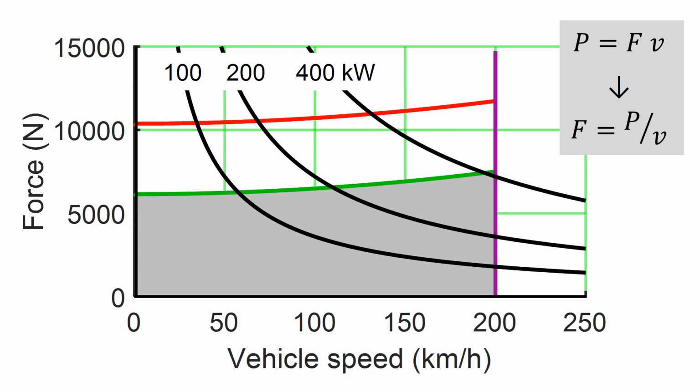Changing requirements does not influence the rolling resistance and aerodynamic resistance of a given vehicle, but by accepting lower acceleration and lower gradient ability at high speed, the traction power demand can be reduced. For medium performance cars, it's often reasonable to have a maximum traction power of about 150 kilowatt.